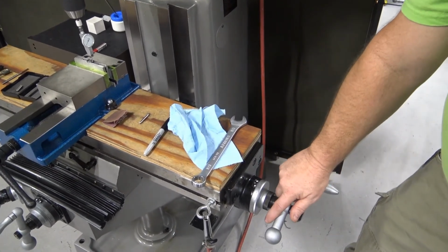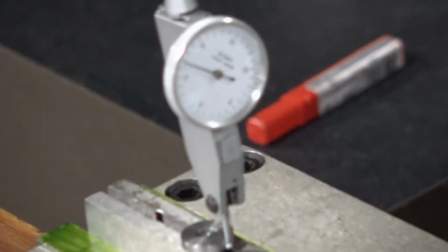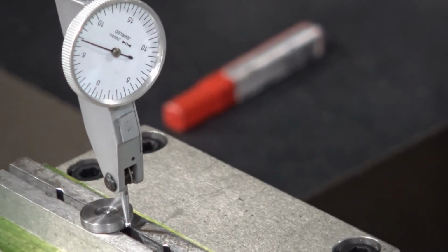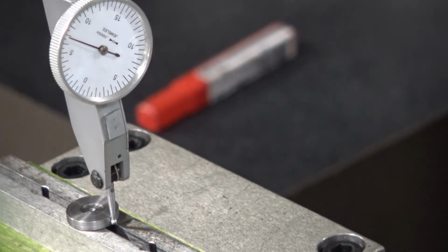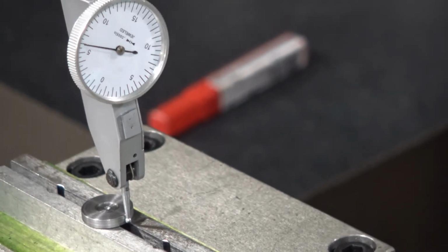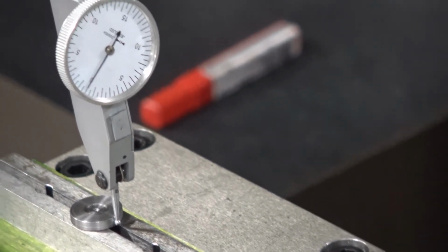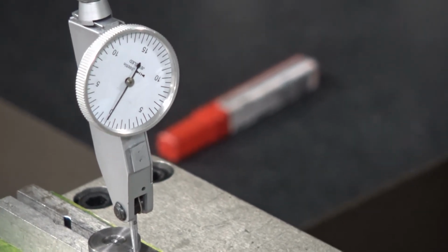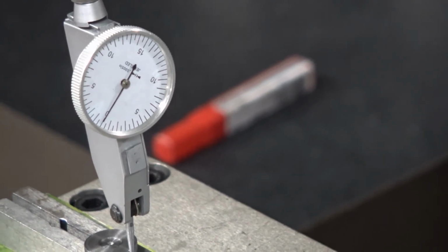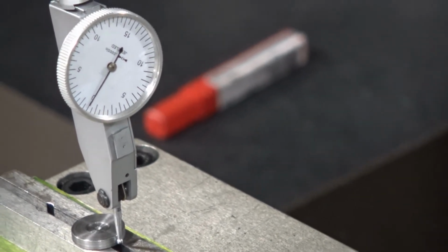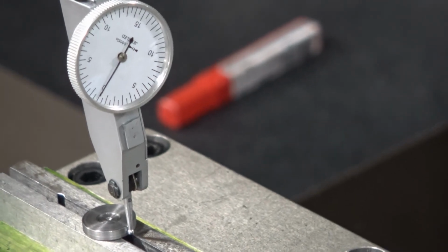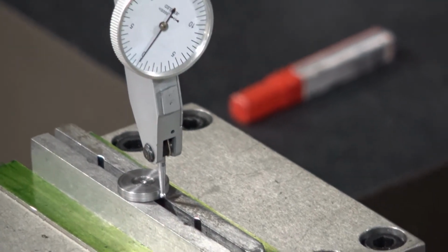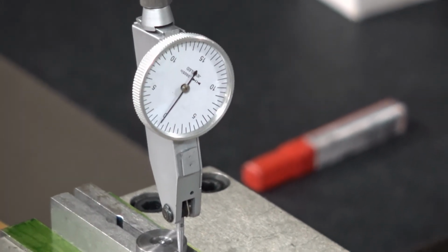So we're going to move counterclockwise where we're at right now and see that the needle has started to move off of 0. And now I'm going to come back clockwise. So if I say clockwise into 0, and I dial it as closely to 0 as possible, okay? And I only move 5 to 7 thousandths off of 0. These indicators have between 30 and 45 thousandths worth of travel. No way did I get anywhere near its limit, okay?